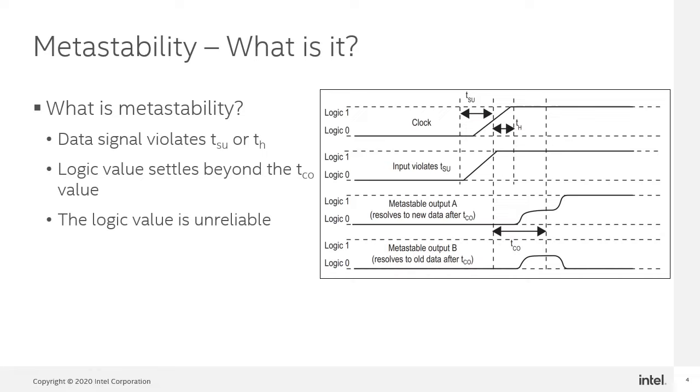If the metastable signal does not resolve to a low or high state before it reaches the next design register, it could cause the system to fail. Failure can occur when the time it takes for a stable state of 1 or 0 exceeds the allotted time, which is the register's clocked out, plus any timing slack in the path from the register. When a metastable signal does not resolve in the allotted time, a logic failure can result if the destination logic observes inconsistent logic states.